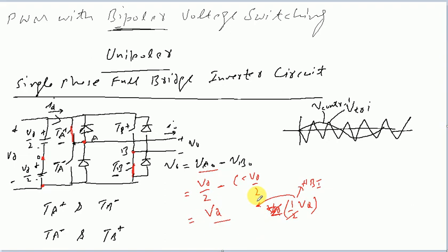The previous analysis that we carried out is applicable here, and the rest of the discussion that we had in detail, that the peak amplitude of the fundamental frequency component of the output voltage is linearly related with the amplitude modulation ratio, provided that the amplitude modulation ratio is less than 1. If it is greater than 1, then we have this other equation, somewhere in between, and 4 by pi into Vd is the maximum value of that.